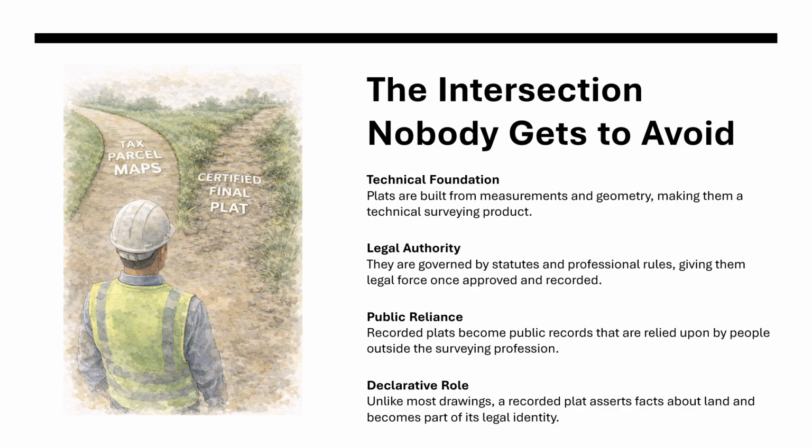And this is where a common misunderstanding shows up for students. Because plats are drafted in CAD, it's easy to mentally group them with other drawings you've already worked with. But legally, they behave very differently. While a grading plan offers guidance, a design drawing proposes intent. A recorded plat does something far more final. It declares, and that declarative role is what separates plats from almost every other survey product you will encounter. Once recorded, a plat is no longer just part of a project. It becomes part of the land's legal identity.